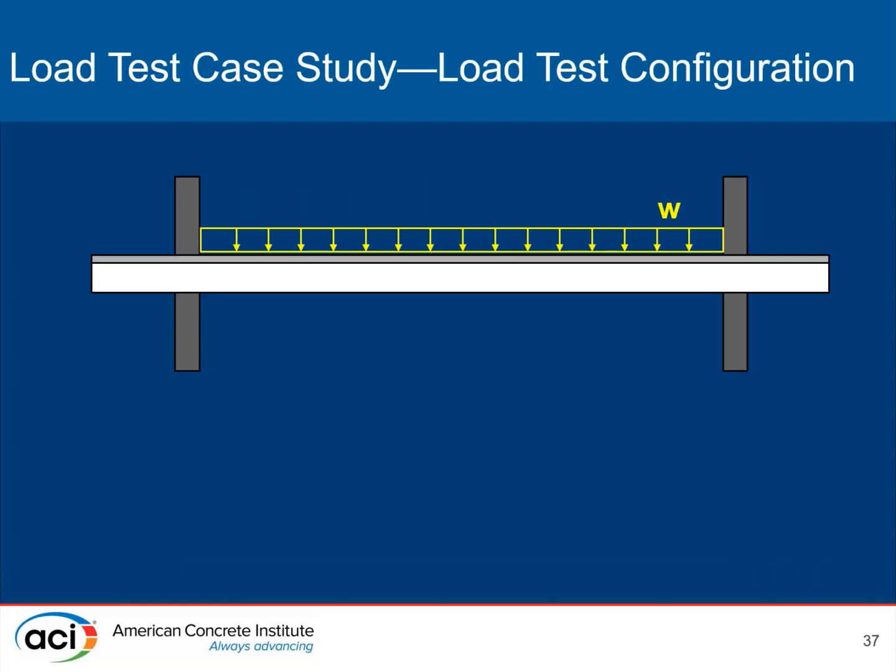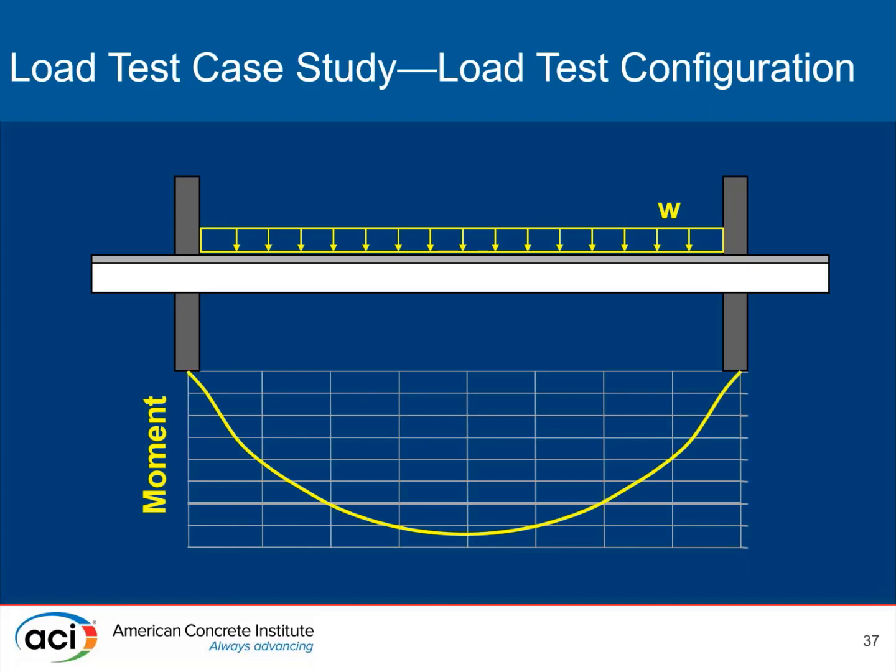So, the load test configuration that was selected: obviously, we have a moment that is generated from a distributed load, and this load test approximated these loads by first detaching, and I'll show a picture of this in a minute, but isolating the member, and then including point loads at the third points to create a similar condition with respect to the loading.